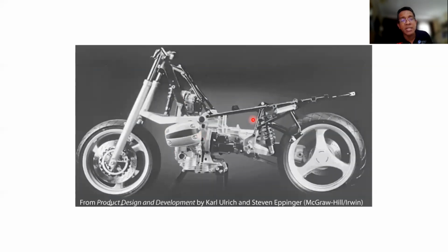So engine mass and frame mass. They combine together and they can have a lighter bike, a lighter motorcycle, and then can increase the speed and improve fuel consumption in terms of design. So that is all related to the design and how they combine. They make an integral design of this motorcycle to exploit everything. And the practice of implementing multiple functions using a single physical element is called function sharing. They share all those functions in one chunk or two chunks. So they call it function sharing.